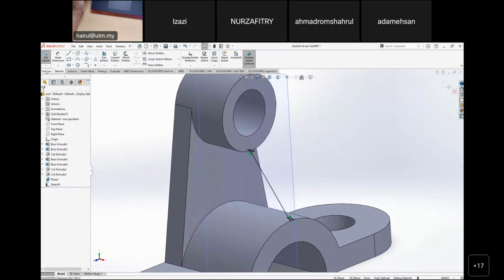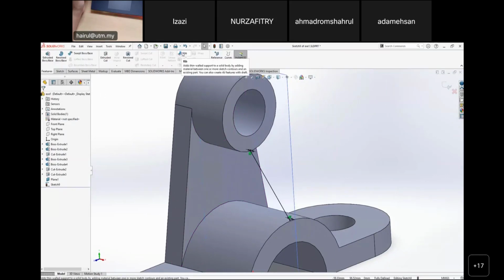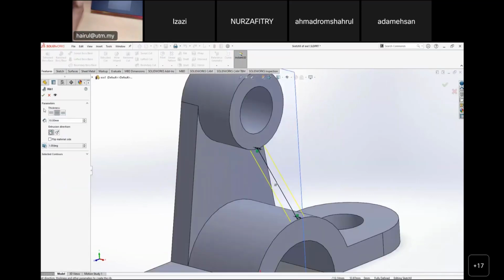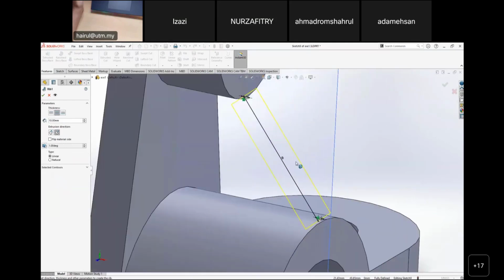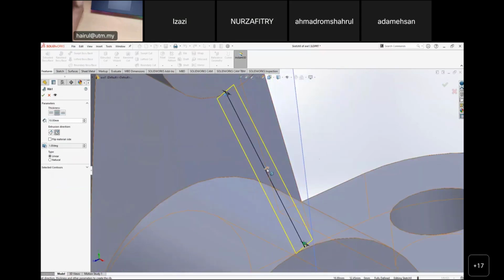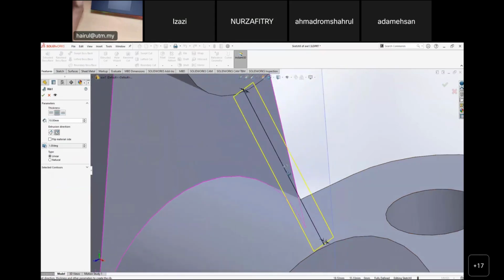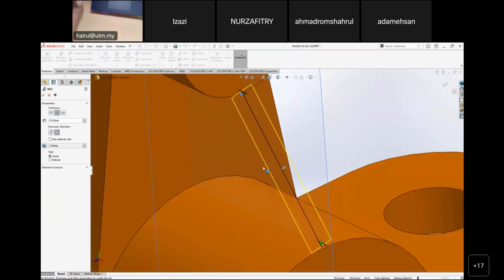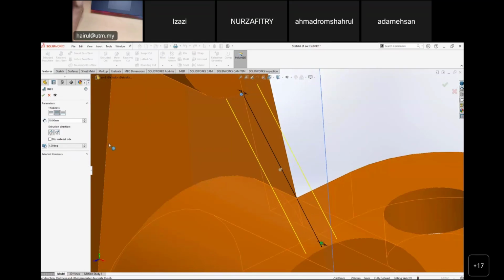Okay, in Solidworks, under Features here, we have what they call Rib. See the rib? A rib makes a thin wall. Here there is a rib. Sometimes, on the menu on your left, you look at the orientation. Certain orientation is like this. If it's like this, it's not the right orientation, because the flow of your material cannot protrude in that direction. You see the arrow, the protruding direction, you want the material to go downward. Make sure you go for the first option.